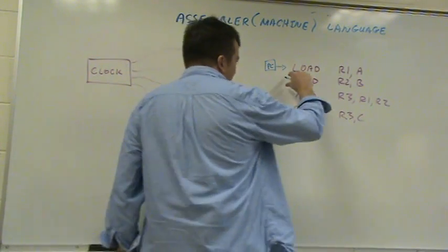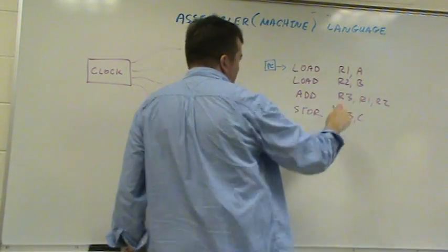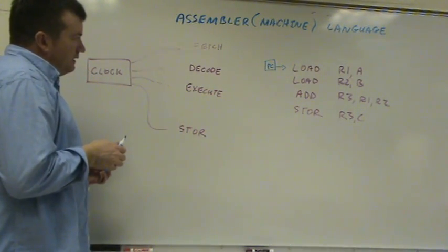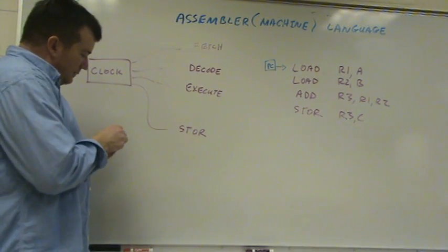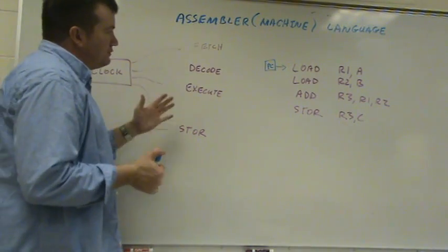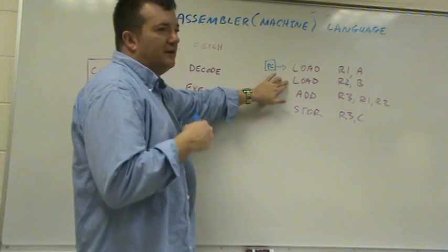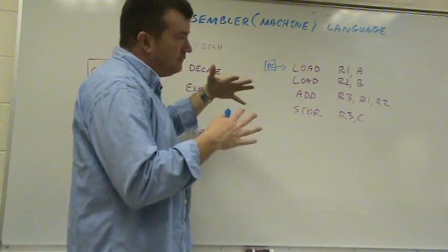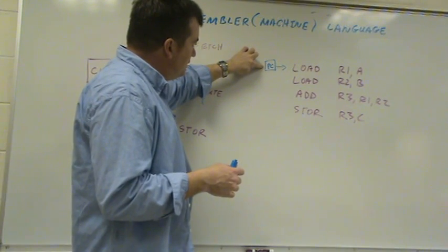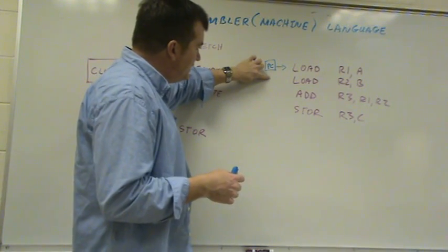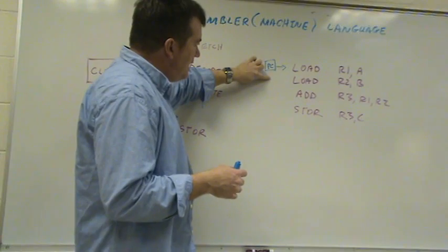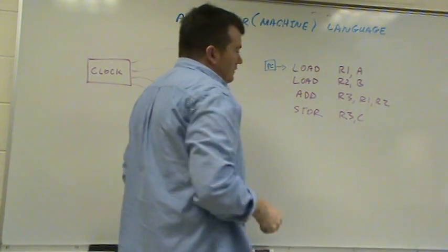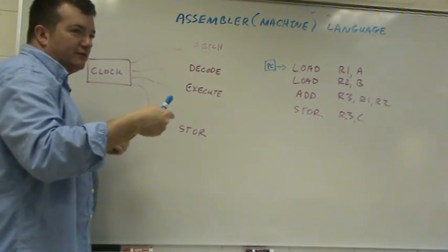And that way we can then capture these zeros and ones in an instruction register. Then the next step would be to figure out what the instruction is doing. It could be doing an add. So the first step is to get the instruction, and that involves adding something to the program counter to get to the next instruction, and then latching all of the bits for it into the instruction register.